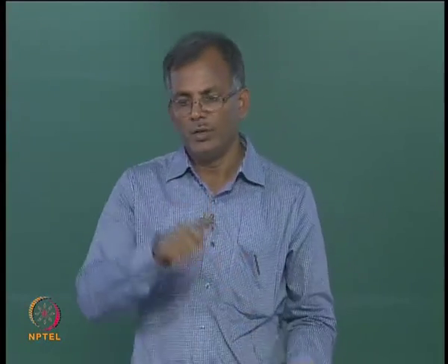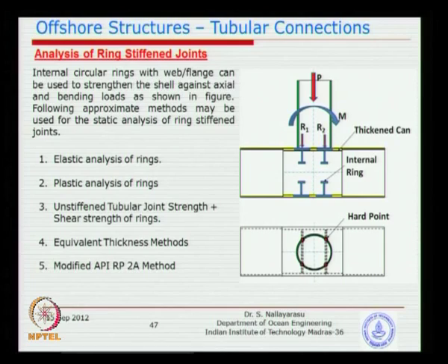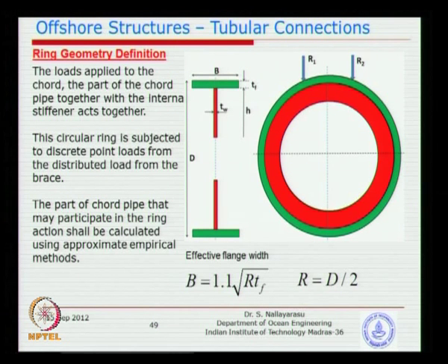What about moment? When you have the moment applied in this fashion, you will have 2 points carrying compressive load, the other 2 points carrying tension load. So you have to sum it up. And then what about the out of plane moment? One point will carry a combination of axial plus in plane bending plus out of plane bending. So one of the corner points is going to carry almost the maximum load. All other points will carry slightly less depending on the direction of the moment. So you need to resolve the forces and then carry out such analysis. Of course, if you look at some of the textbooks, you will find equations to solve.